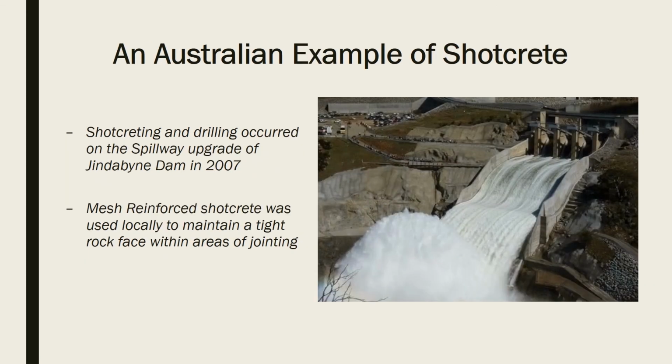Shotcreting and drilling occurred on the spillway upgrade of Jindabyne Dam in 2007. Mesh reinforced shotcrete was employed and used locally to maintain a tight rock face within areas of jointing.